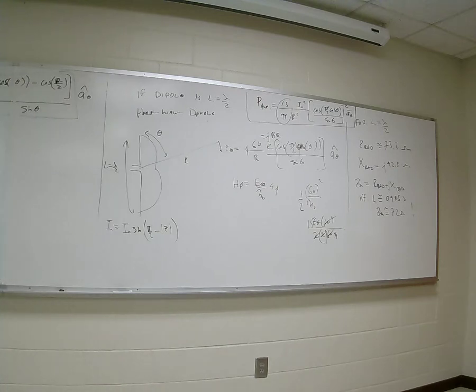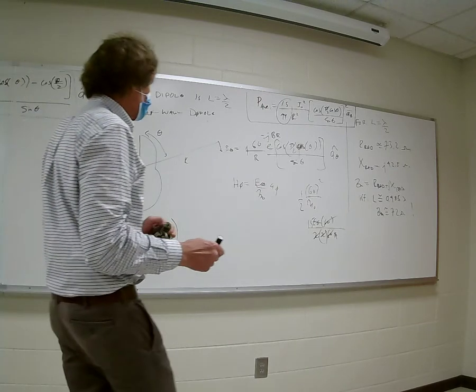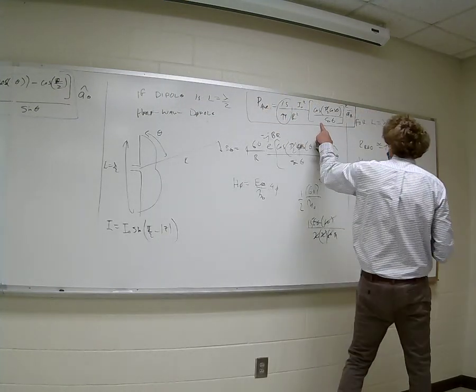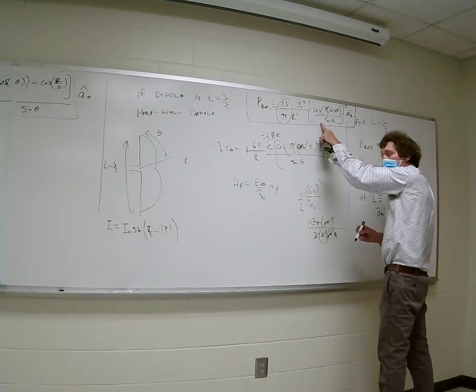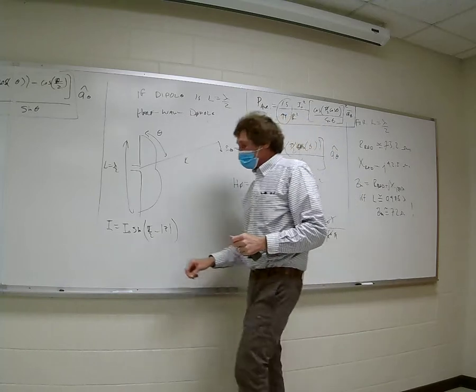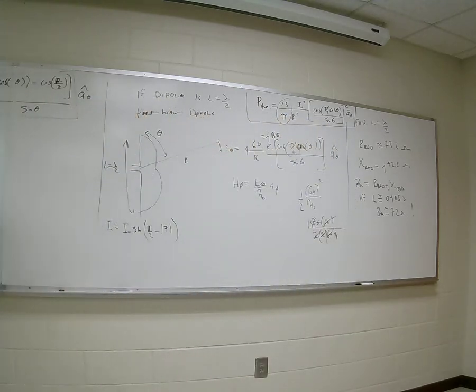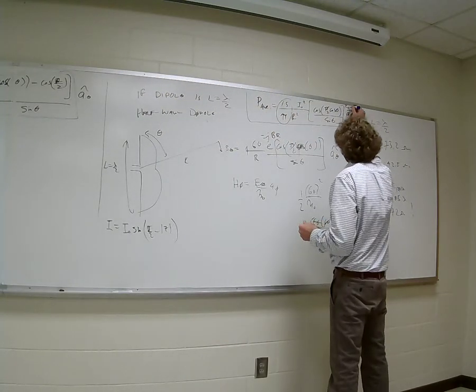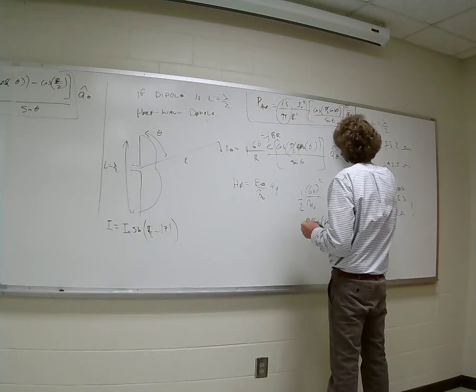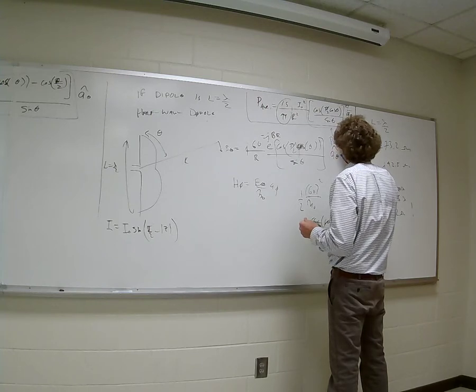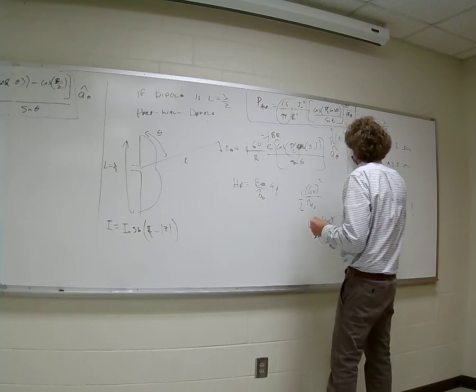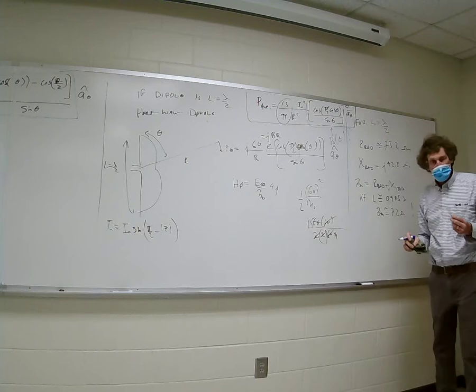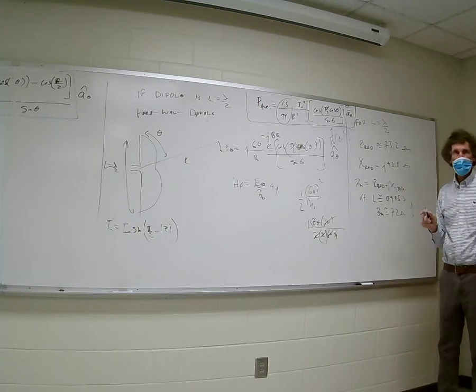Now, the interesting and important thing is you see this cosine of pi over 2 cosine theta over sine theta, squared? In Wentworth's book, he's going to call that f of theta. And that is really how the power is distributed in an angular fashion. This is really P normalized of theta. You can't just look at that and know, but if you work with it, you know.